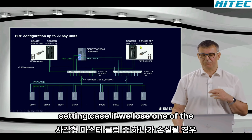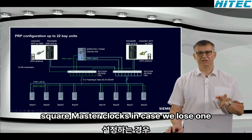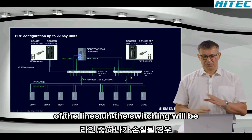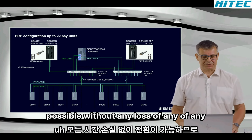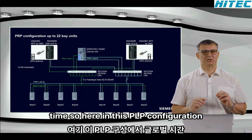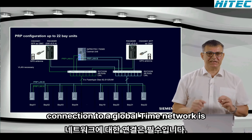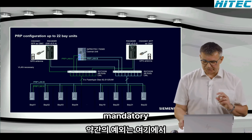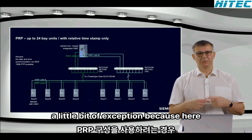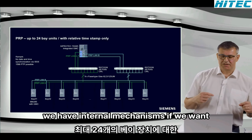So that in case we lose one of these grandmaster clocks, or in case we lose one of the LANs, the switching will be possible without any loss of time. So in this PRB configuration, the connection to a global time network is mandatory. A little bit of an exception, because here we have internal mechanisms.